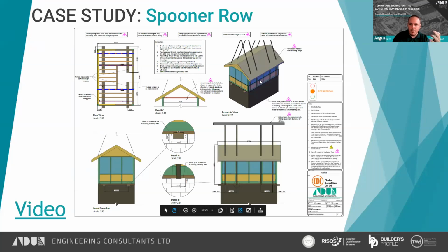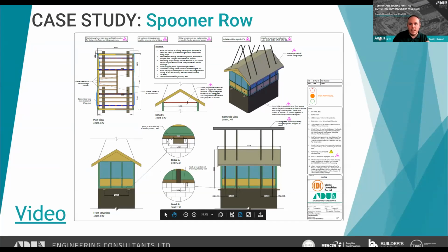So from site visits, it was clear that the predominant loading is in this wall. I'm going to draw with a pen. This wall and this wall. I'll make that a bit thicker. Like that wall and that wall, they support the roof loads here and here, which come down this wall here and here. The end walls are only really carrying the self weight of that timber panel, which is not really a great deal.